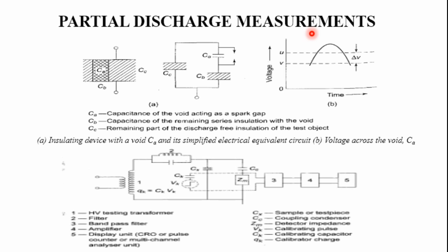In the case of the audio frequency range, wideband or tuned null detectors are also used with a sensitivity of better than 10 microvolts. Other than this, a cathode ray oscilloscope is also used as a detector if too high a sensitivity is not required. So the selection of the detector depends on the type of bridge, the measurement, and the sensitivity which is required in the particular application.